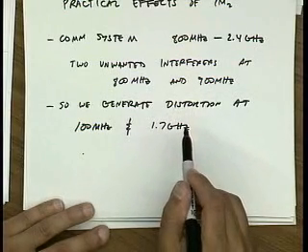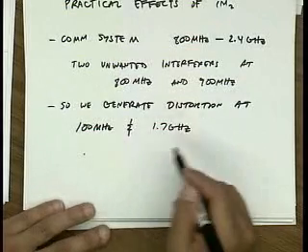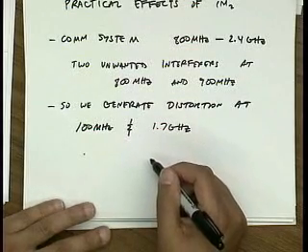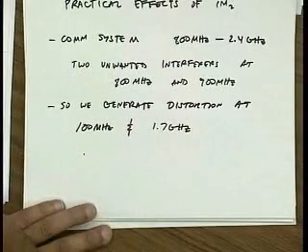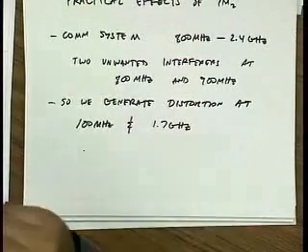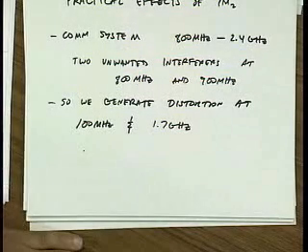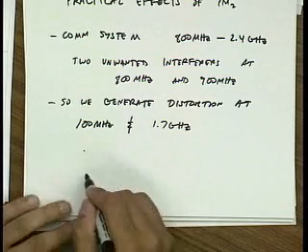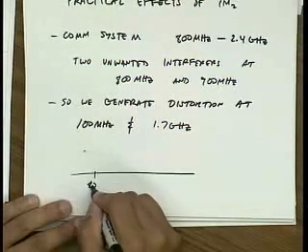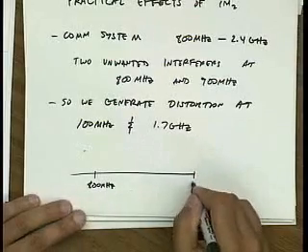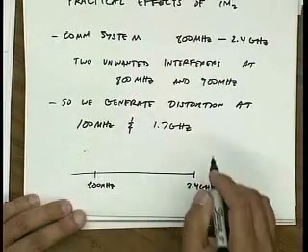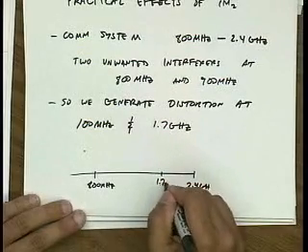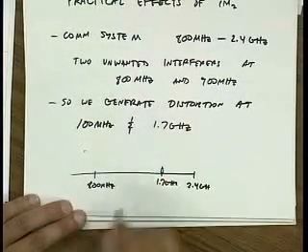Okay? Now you might say, well, these distortion terms are always really small, right? That's the whole assumption for weak nonlinear analysis. So what's the problem? Well, if you think all the way back to lecture 1, we talked about the fundamental issue with wireless communication: the dynamic range of signals varies greatly. Sometimes your signal is strong, sometimes it's weak. So let's say we draw a band where your signal at 1.7 gigahertz, say here, is very weak.